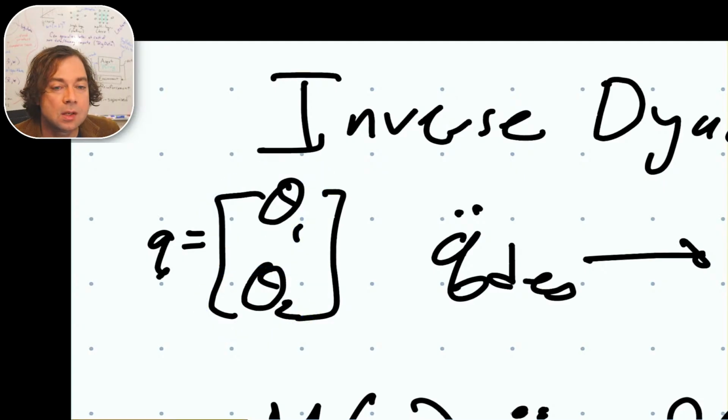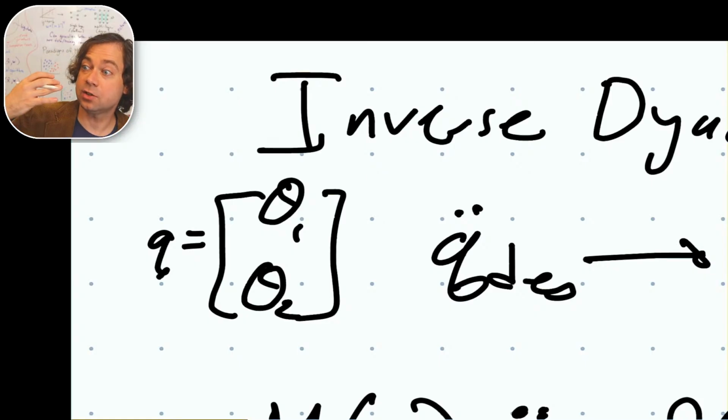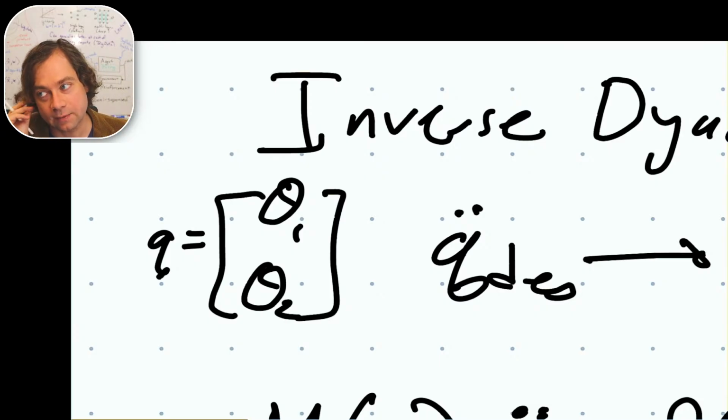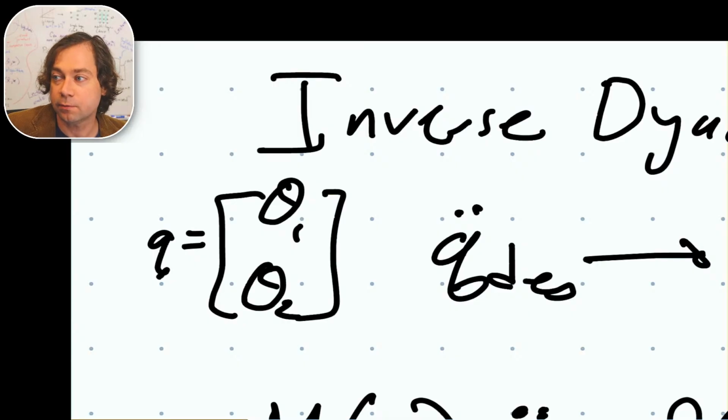A good check to make sure this is all going to be working is, what if we command our accelerations to be 0? And if our velocities are 0, this thing should just stay in place. It should not move. That's a good check to make sure you have inverse dynamics working. Irrespective of whether this thing starts off in a down position or in some other weird position, it should be applying torques in such a way to keep the pendulum from accelerating.